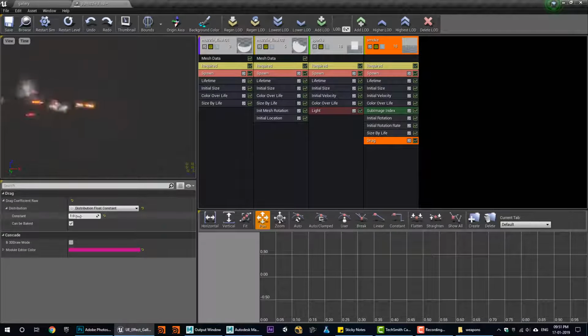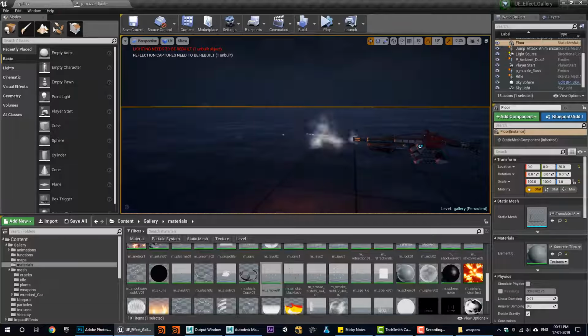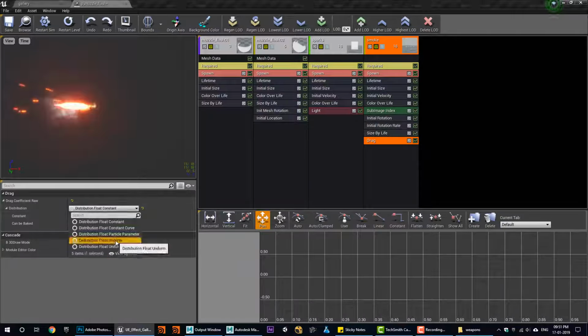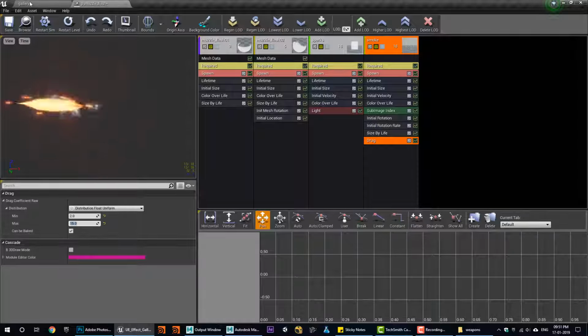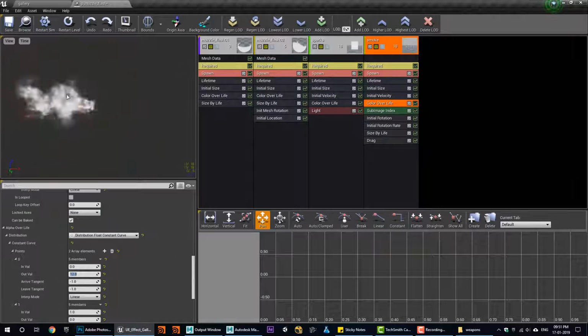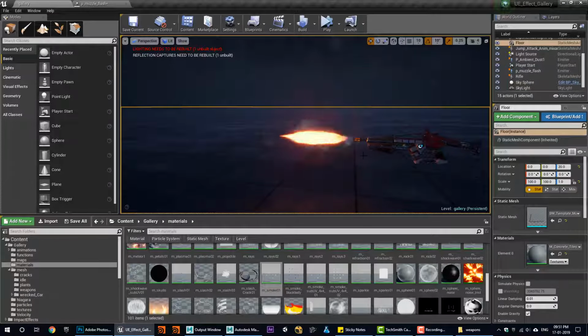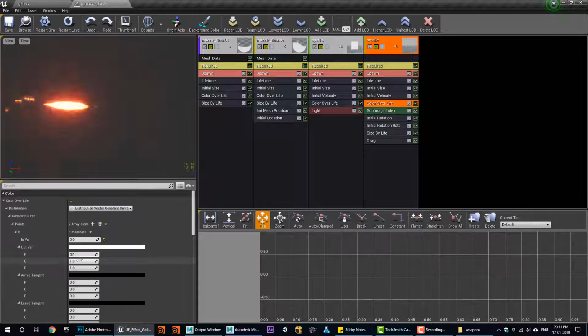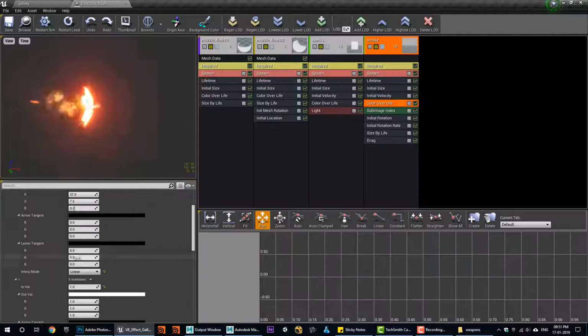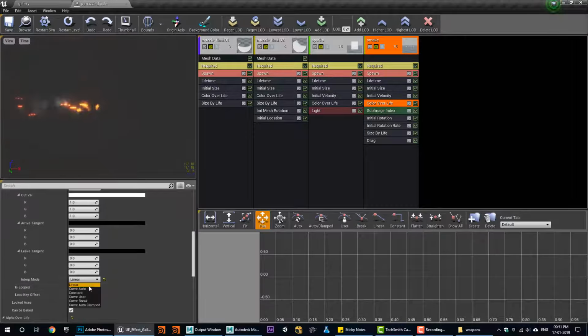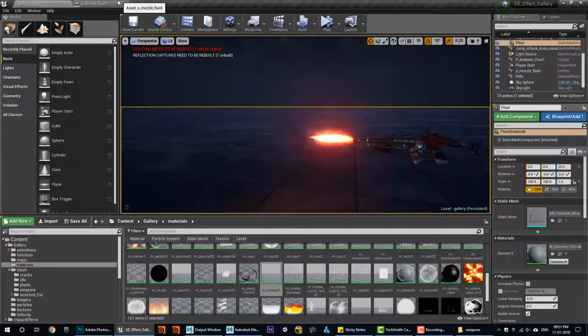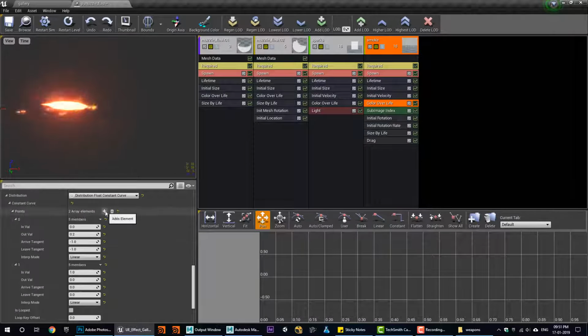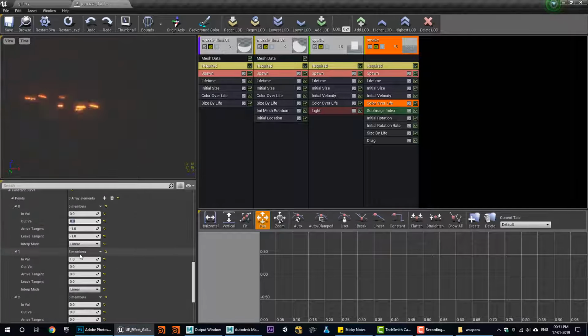and if I play it all, not looking nice, I know, but you need to use drag, and I will use random drag 2 and 15, and I will decrease the alpha, I think 0.2, just for a feel of smoke, and maybe I will change color, and starting it should be like red because of light, and on 5 it's white again, and alpha I will use at 0 it's 0, at 0.3 it's 0.1, and at 1 it's 0,